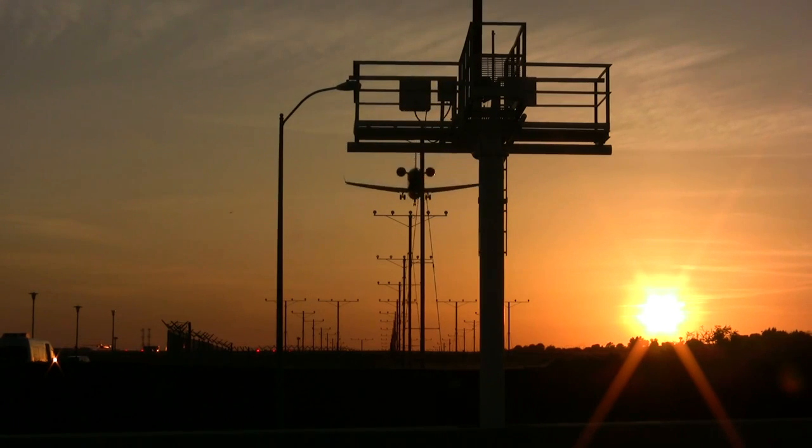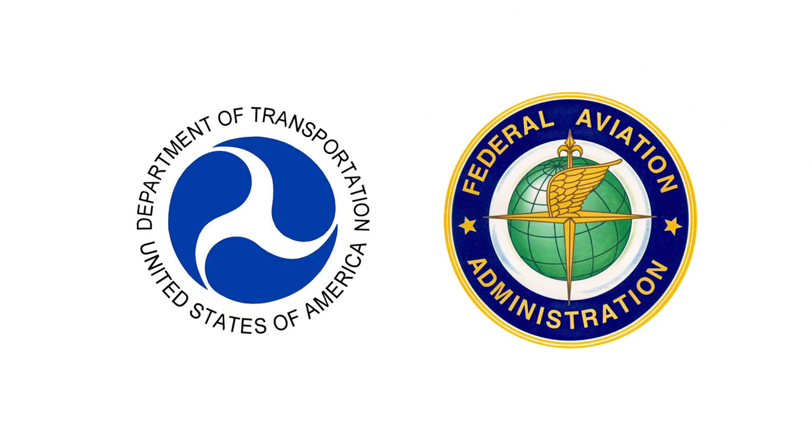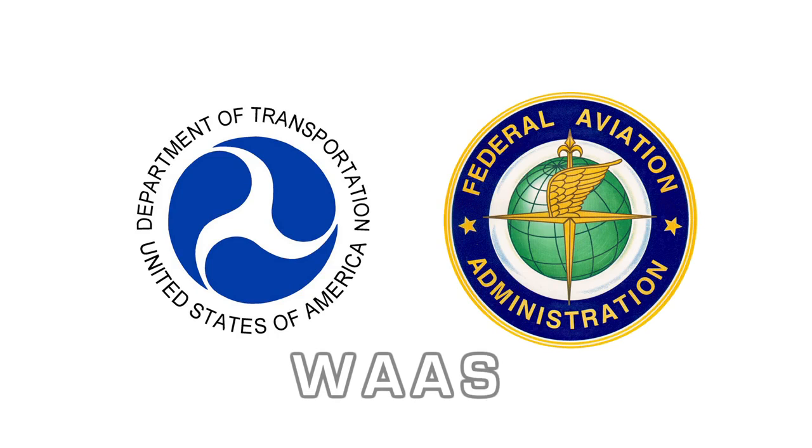Prior to the development of SBAS, GPS was not able to provide the accuracy or integrity to achieve Cat 1 minimums during approaches. The FAA and Department of Transportation began development of WAAS in 1994 to allow precision approaches, and in 2003, WAAS was activated for public use.